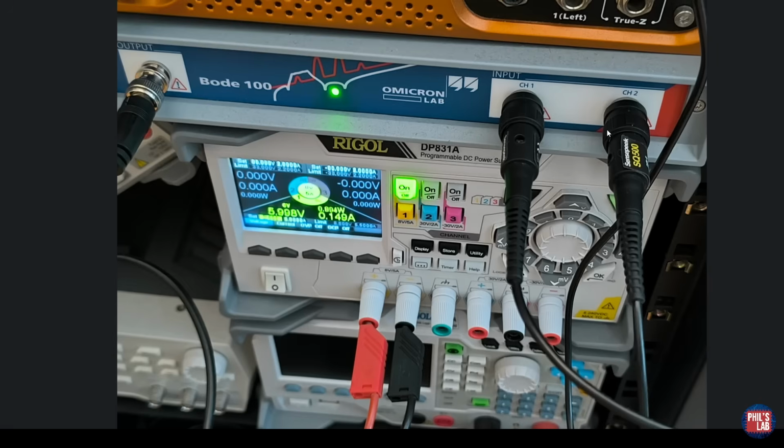In this way, we can do a full gain phase transfer function measurement, the relationship between the output relative to the input. Given our DC bias plus AC signal on top, we can figure out the ratio of AC signals of output to input, and that gives our power supply rejection ratio. I'm using 10x probes for channel 1 and channel 2, and the whole board, this LDO test board, is powered by a lab power supply. We can later alter the input voltage to see what effect that has on the power supply rejection ratio, and I've also set up the LDO test board to sink 150 milliamps of current, which we'll see later on.